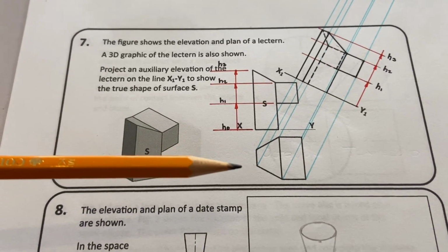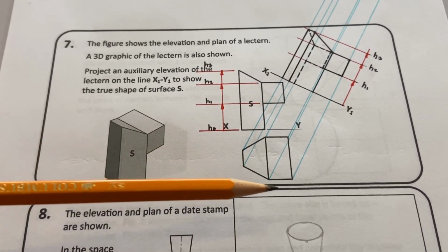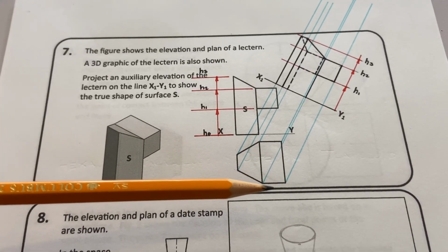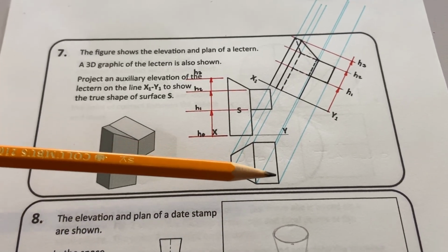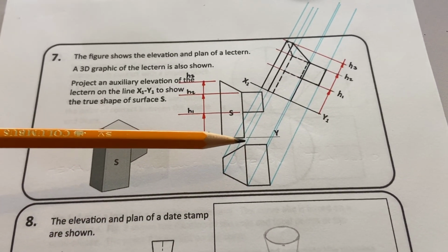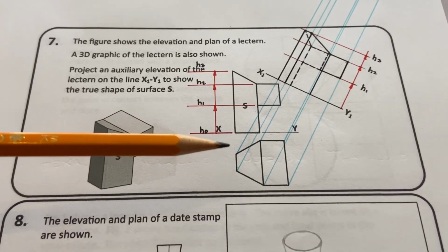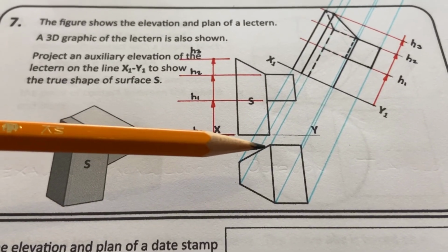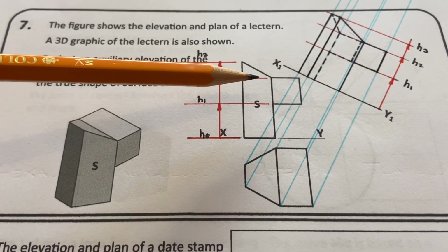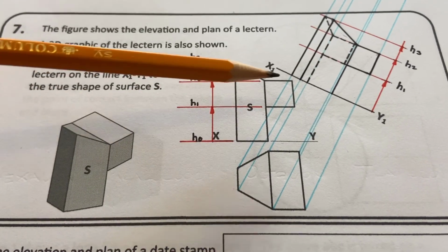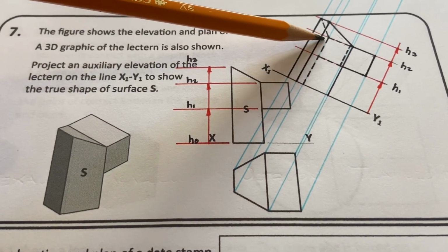So once we've dealt with the surfaces that we can see, which is the front, surface S, and this side here, we then have to consider the surfaces that are not visible to us, which will be this area here, this line coming back, and this one here. But again, the same principles apply. So if we look at this line here, it begins there on H0 and it goes all the way up to H2. So when we follow that line up there, it starts at H0 and goes all the way up to H2.